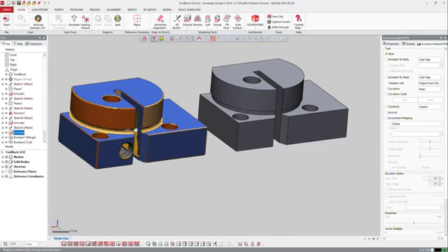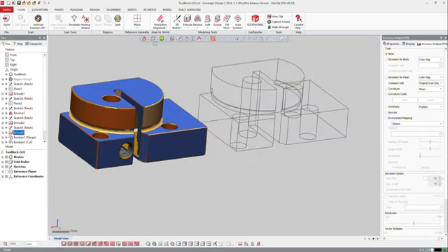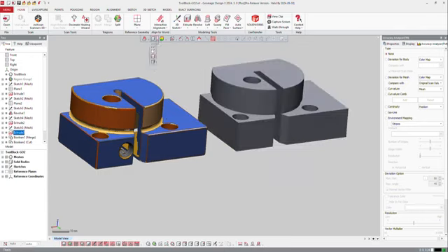Then you can also display your CAD by displaying the CAD as wireframe with hidden edges. And then you can continue with shaded display and shaded display with edges, which is the default. Then you can also control the zoom.